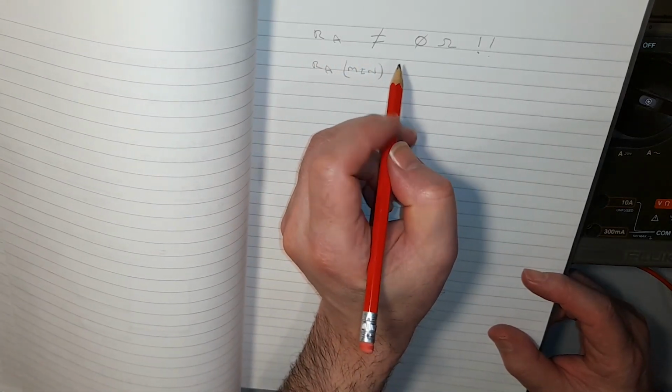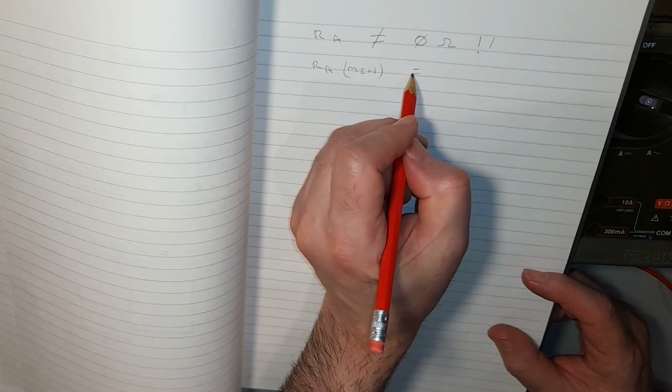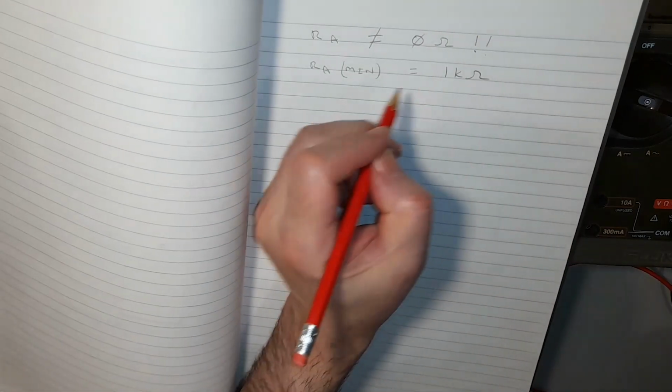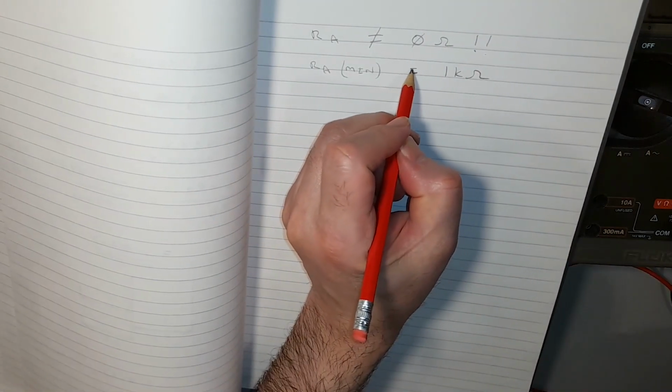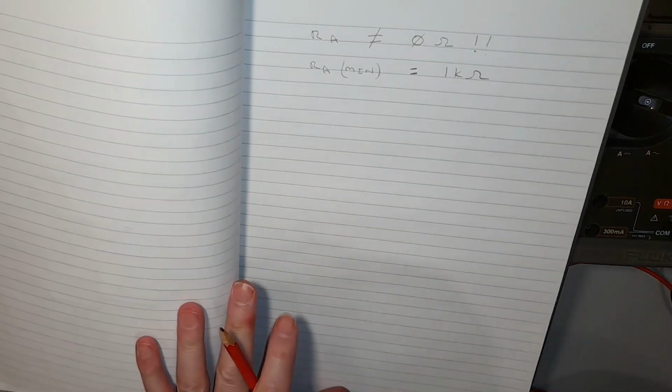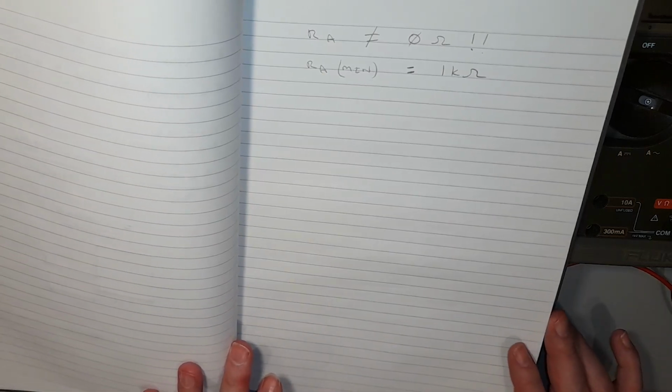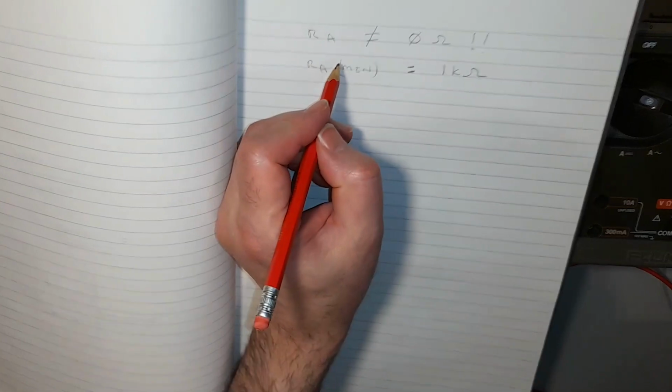Well, a safe value I think we've found is approximately 1 kilo ohm, and that's on the data sheet, and that's where the data sheet kind of starts. But I've got it down to 200 ohms and 100 ohms round about there, but we can't tell really what was going on inside the chip and how badly it was being affected with such a low resistor.